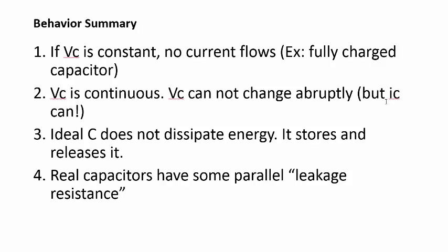But in reality, nothing is ideal, and there is some parallel leakage resistance, we call it. So if you were to model a non-ideal capacitor, you would have a capacitor in parallel with a small resistance. Excuse me, large resistance.